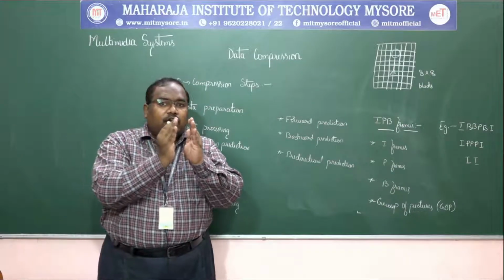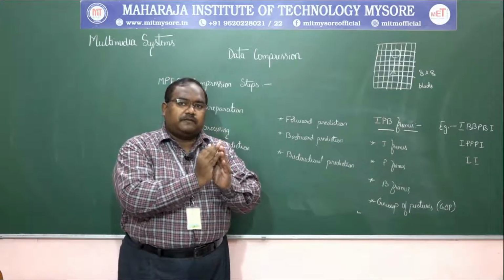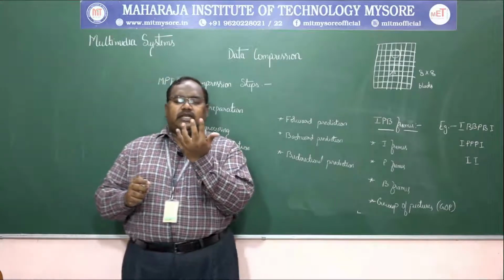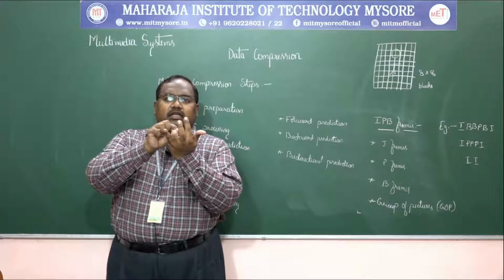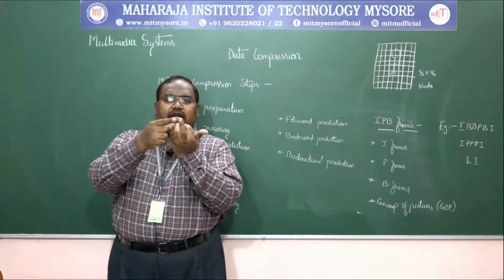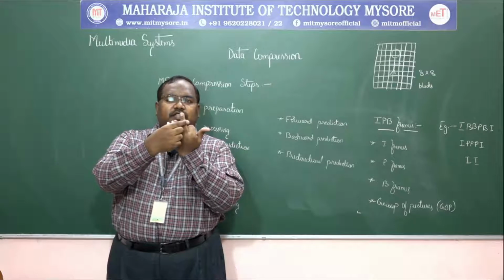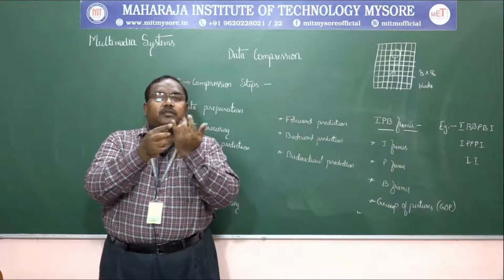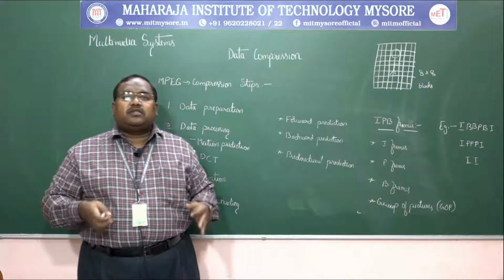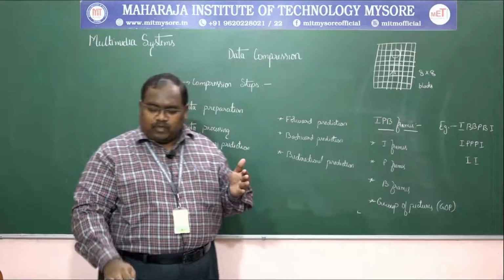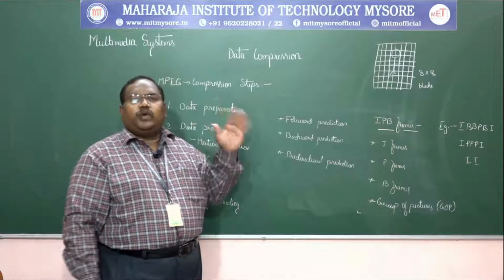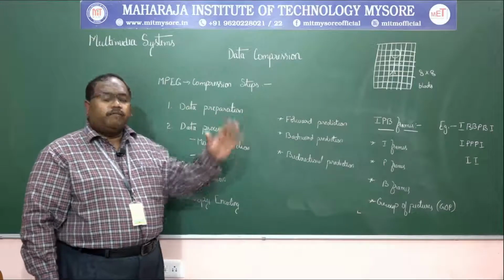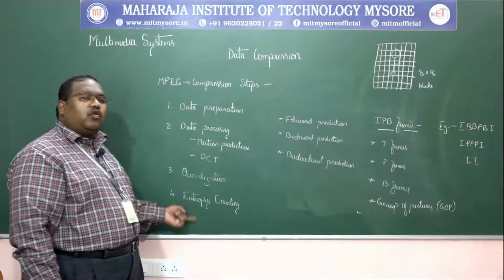So when DC components are used only to represent, obviously what happens here, the size is totally reduced. Means if there are 4 things like this, we delete the higher frequency range and retain the DC coefficient, that lower frequency range, and quantize into group. So combined we have the storage reduced, means lesser data we have, so the representation of data becomes very less. Obviously the size of the video becomes very less. So fourth one, when the storage is less, we need to encode it. That is the fourth stage, that is entropy encoding.